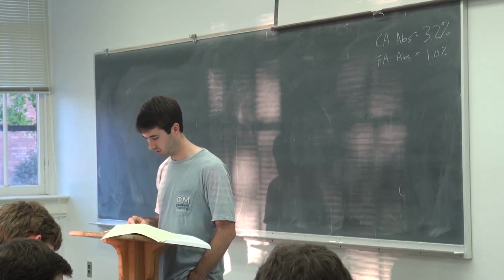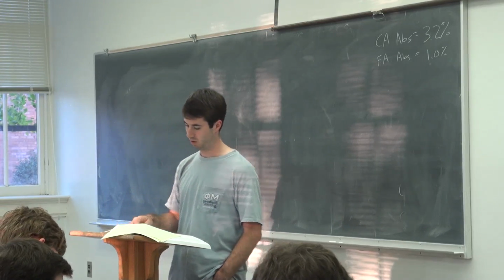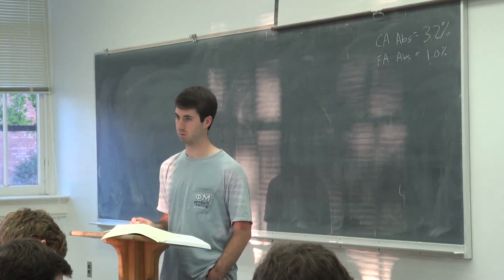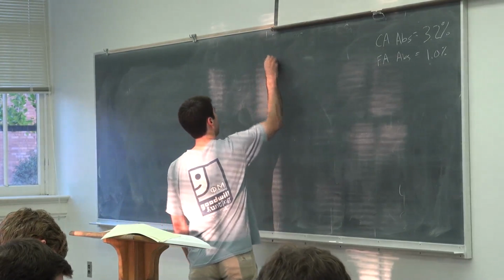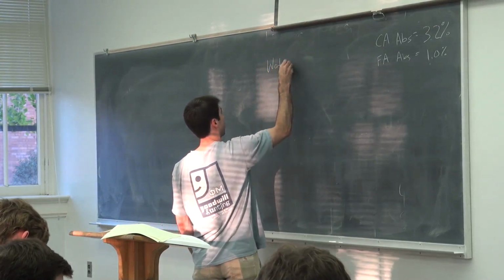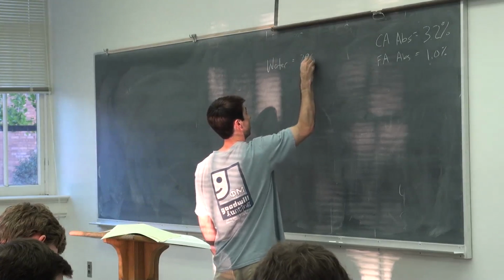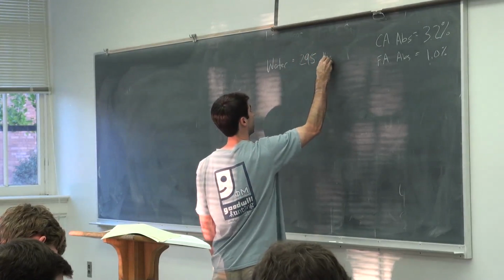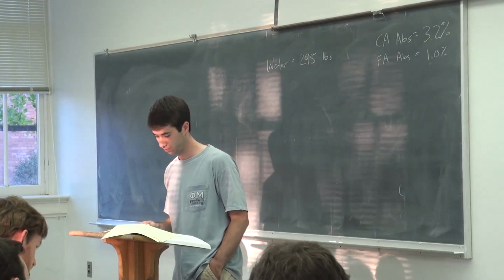We got 1 inch aggregate, look at that table at the top. We do have air entrainment. We want a slump of 3 to 4 inches. What's our target water? Is that gallons? Pounds. 295 pounds. What do we do next?